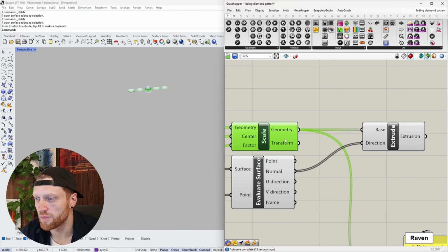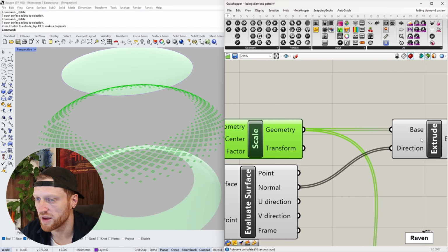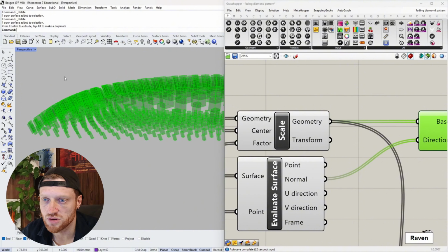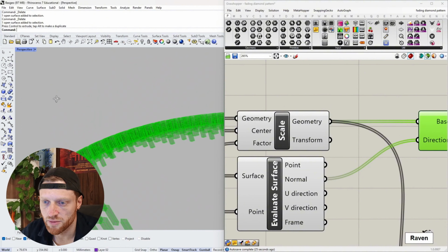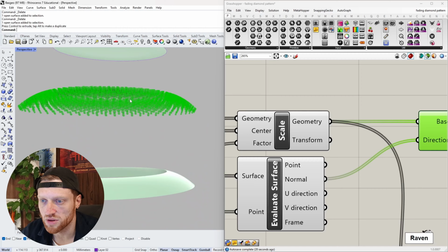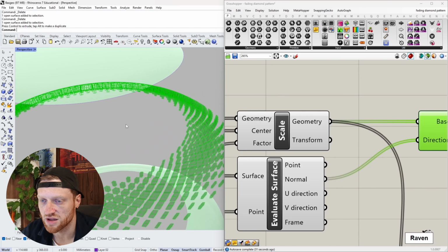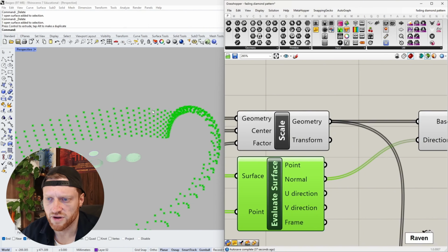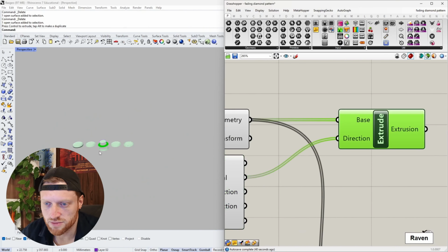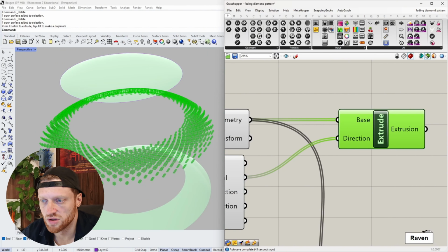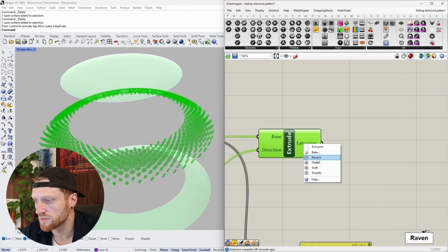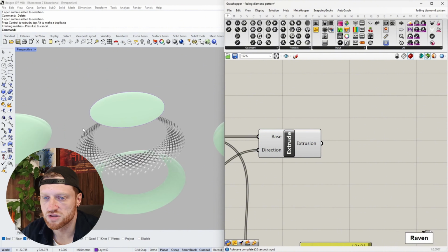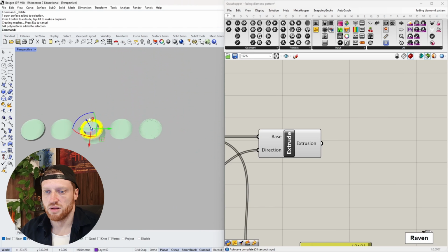But also, if I basically take my geometry here and I apply the extrusion according to the normal that I get from the evaluate surface, then it does look like it did it correct. It looks like it was extruded in the normal direction of each of the individual faces and not according to these crazy patterns here. So I'm wondering if it's just a graphic issue or if I missed something else. But because it's working, I can just continue now and basically bake this, group them, and that's it. And now you say, but yeah, you have a gap here. I mean, yes, I do.